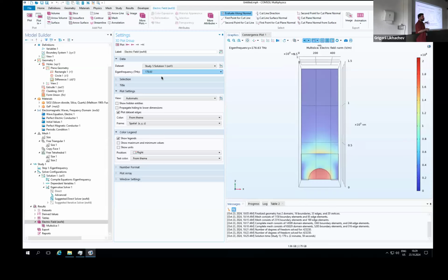So I gave you these formulas, but it's pretty straightforward. If you want to implement it in Python, it's just a couple of derivatives, and you can get all your parameters from just this S11 parameter. So this is actually all. I hope you learned something. I hope you'll do some exercise, but at least I told you how those configurations change and how, if you want to simulate the dispersion of this resonator, you can do it.